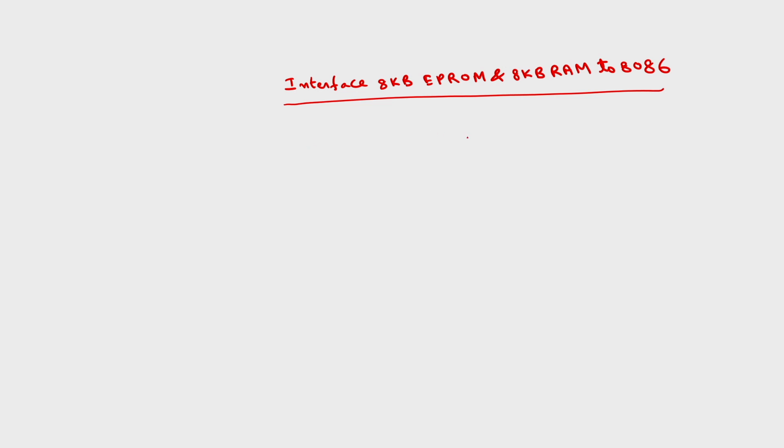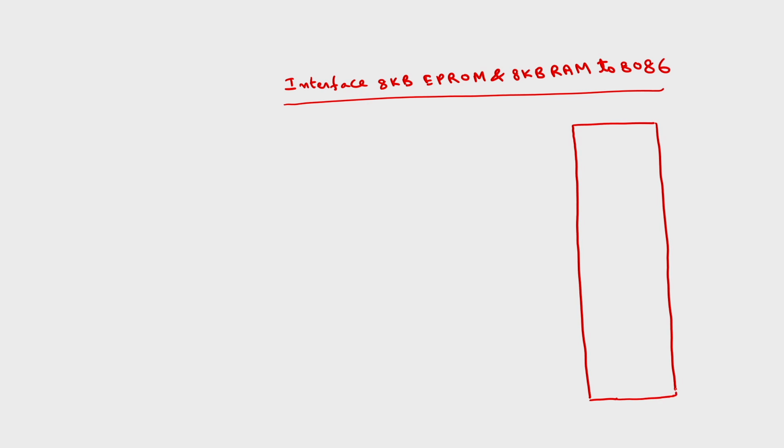We assumed that, out of the 1 megabyte, I want to interface this EPROM in the last 8 kilobytes of locations. So the ending address will be FFFFFH.